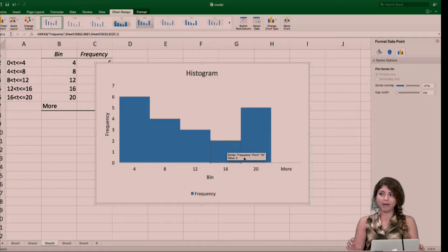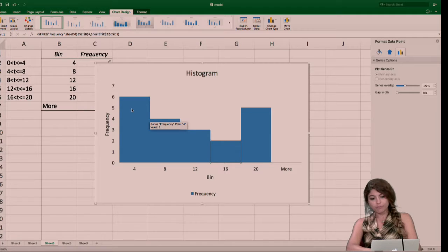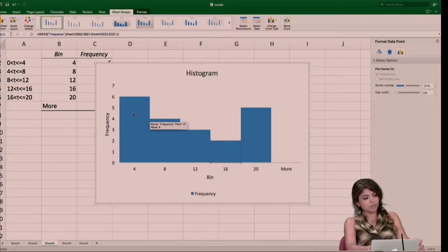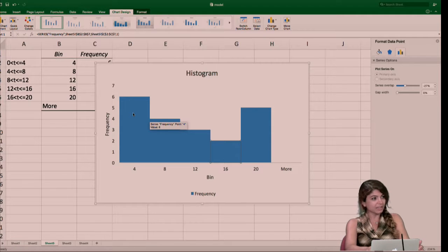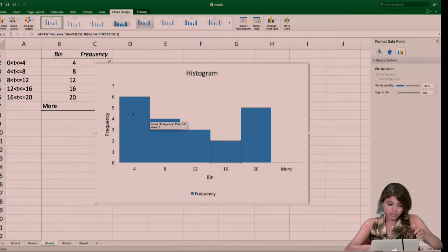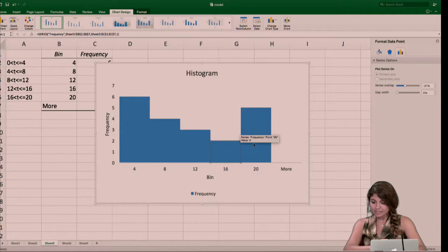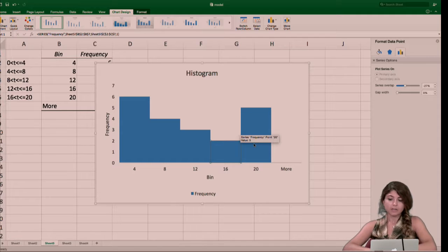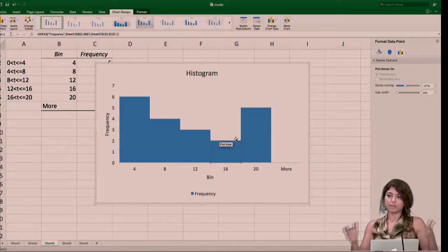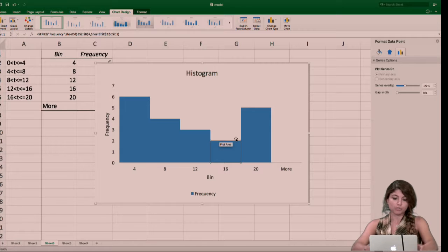If you remember, we had a bathtub curve for the reliability, and you can see that here. Have you ever heard that the probability of failure when the airplane takes off or lands is higher? At the beginning and at the end of the system operation, the odds are higher. You see the frequency at the beginning and at the end is much higher, because it takes time for the system to reach a stability condition. When the system is not in the boundary condition, but within a stable environment, the odds of failure are much lower.